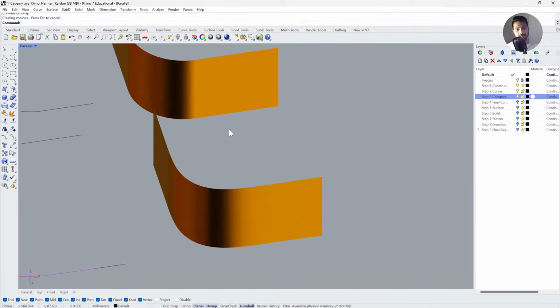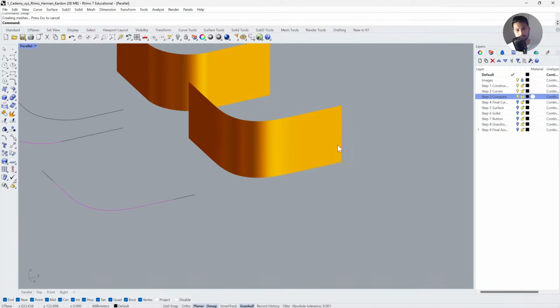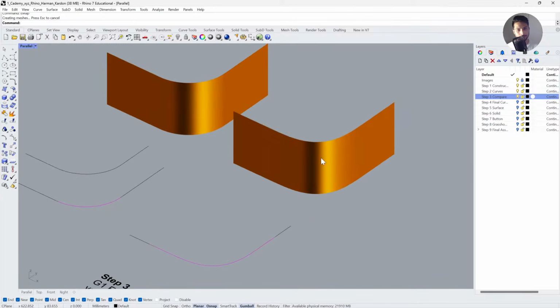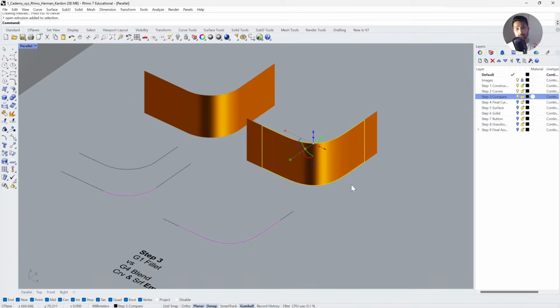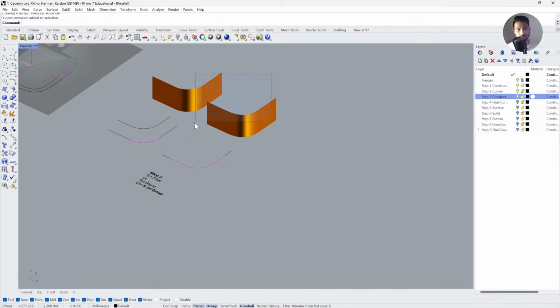Okay, whereas in this case you will not be able to see a sharp highlight because we are transitioning from the flat region to the curved region on a longer patch, and we are slowly ramping up the curvature. So this is going to create better quality surface, better effect in the product. Okay, especially if your product is made out of glossy material.